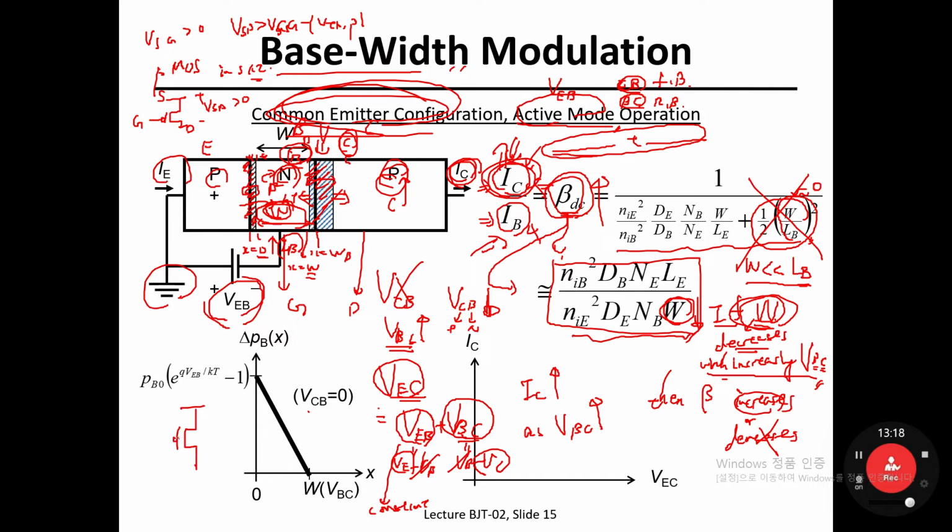Go back to the PMOS with gate, source, drain, now in saturation mode. What about the voltage difference from source to drain? Here the gate to source voltage VSG should be constant for a given value, and for a given source to drain value, your VGD value would also be constant.